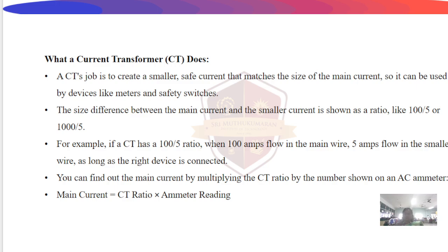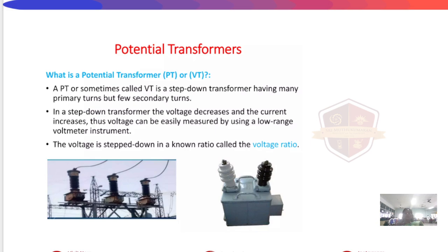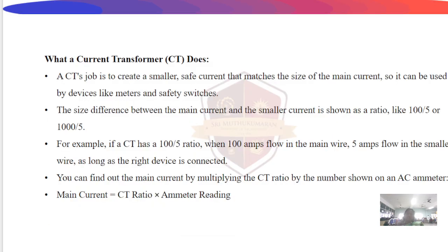The important precaution of the CT is that the secondary of the CT should never be left open while the primary is energized. If it is left open, very high voltage may be induced in the secondary, which can damage the insulation and cause danger.